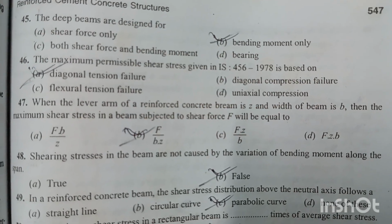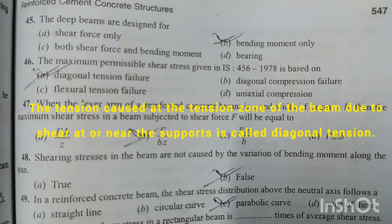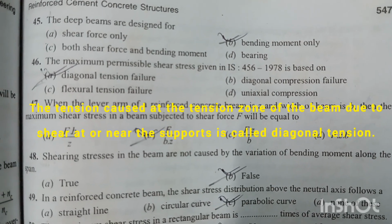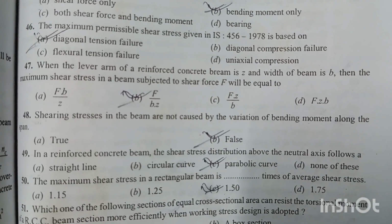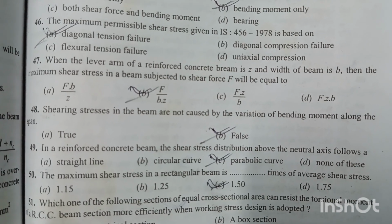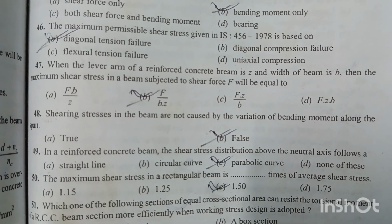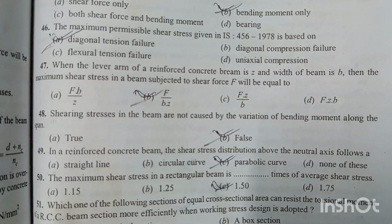Question number 46. The maximum permissible shear stress given in IS 456 1978 is based on diagonal tension failure. Option A is the right answer. Question number 47. When the lever arm of a reinforced concrete beam is z and width of beam is b, then the maximum shear stress in a beam subjected to shear force F will be equal to F by b into z. Option B is the right answer.